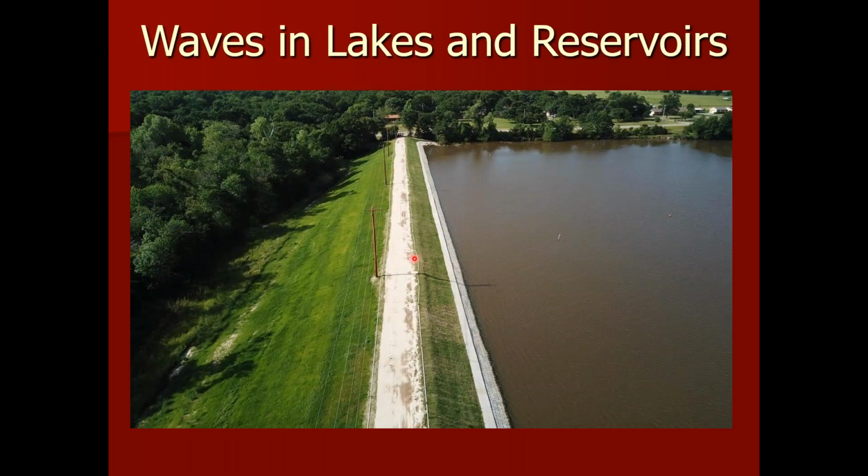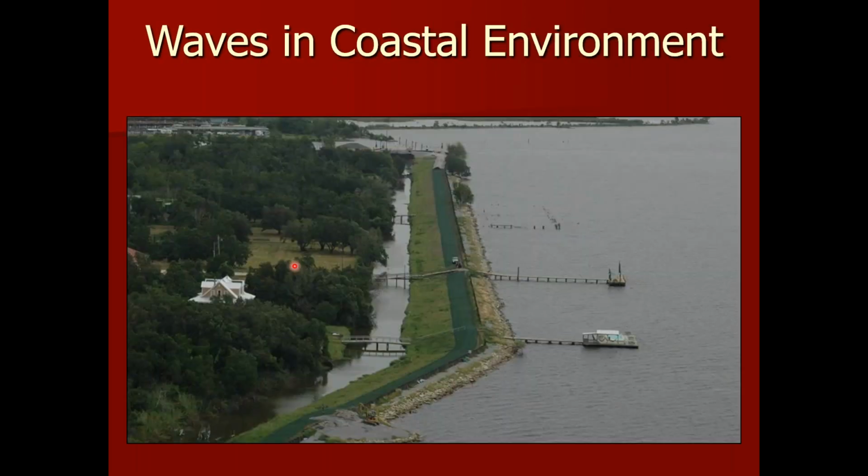This is an application that could experience that type of environment where you have a long fetch length here approaching the embankment. The wave would come over the top and accelerate down this back protected side of the system. Levees, of course, are coastal, so you have much higher waves, much higher periods, frequencies of those waves, and a lot more stress. So it was really important for the Corps of Engineers to understand how these types of products and technologies would work in this unsteady, high-energy overtopping environment.